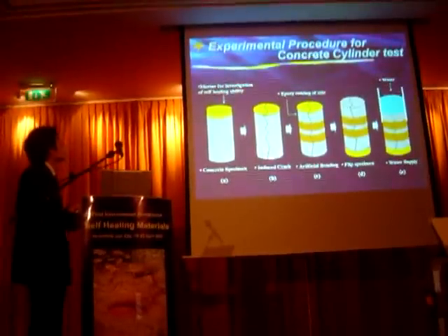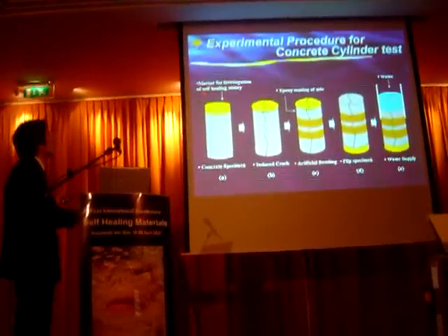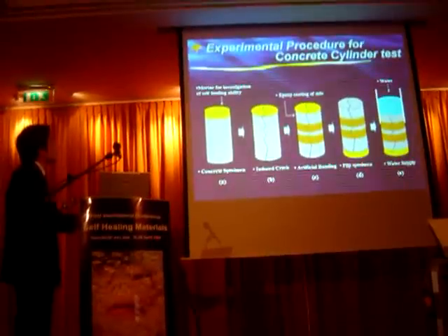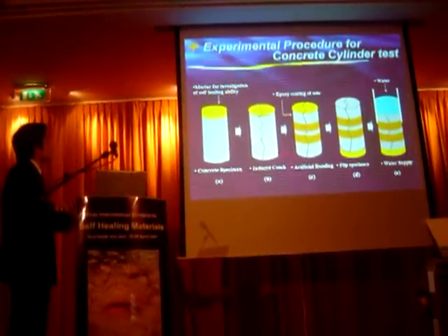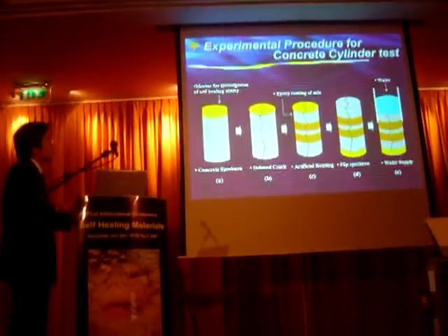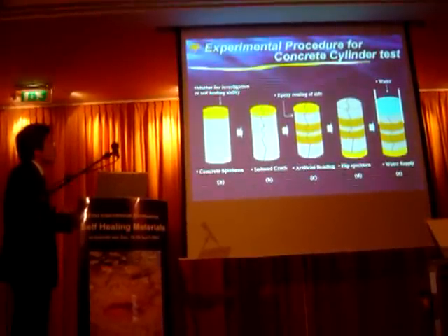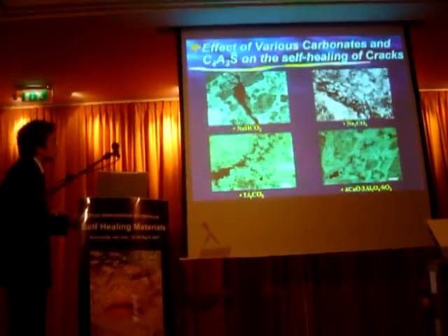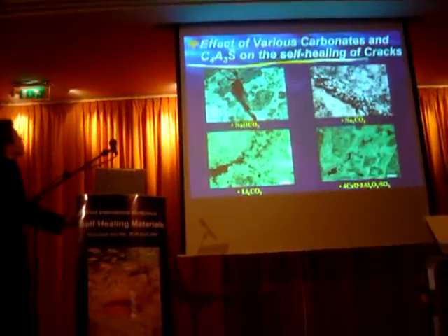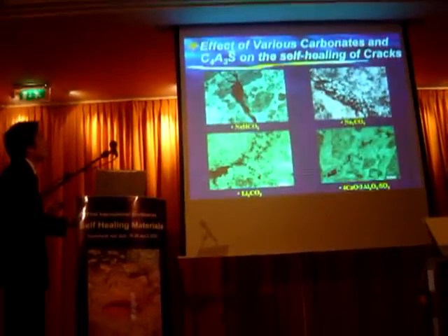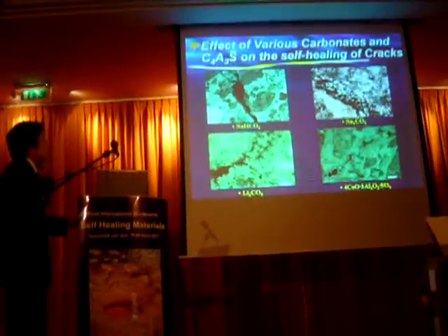And then we also investigated mortars for investigating self-healing abilities using various carbonate. And then we did the test like this. After water supply, we measured this area. So this figure shows the effect of the various carbonate and the calcium sulfoaluminate on the self-healing of cracks in this research.